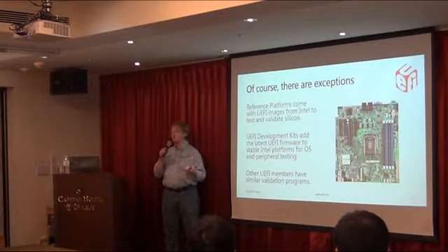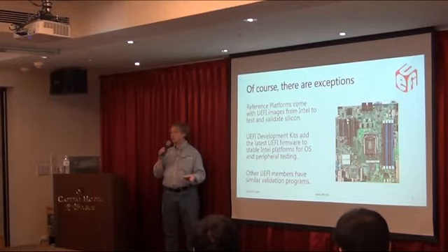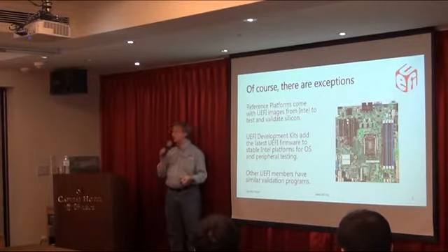If you go to the market, I was already in the computer market here, and buy a board, it's not going to have any debug options. They're all turned off for speed and optimization, and because the competitors shouldn't be looking at how you did things. If you want to debug an option ROM or an OS loader, the debug version of the firmware is really, really handy. You attach a serial port connection to the board, and you get a log, and it tells you why things crashed. We were using it just before I came up here to look at issues between two different versions of our BIOS and why one of the cards wasn't working. So that's really good if you do peripheral testing, if you're a driver developer, if you're writing an OS loader.